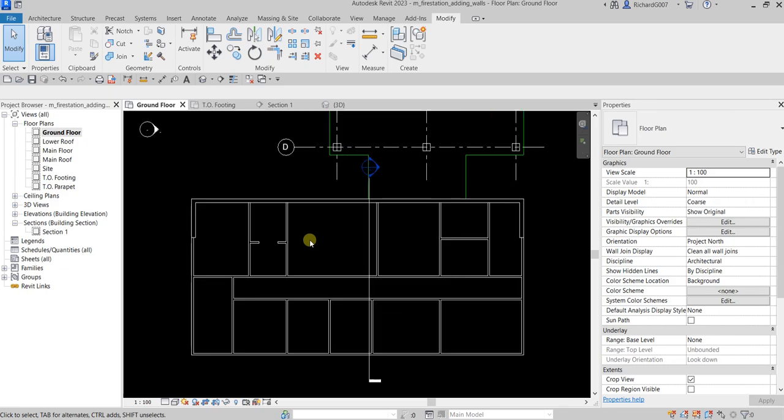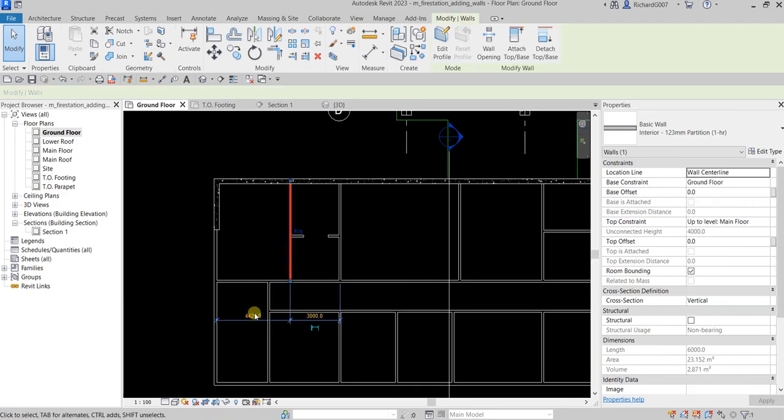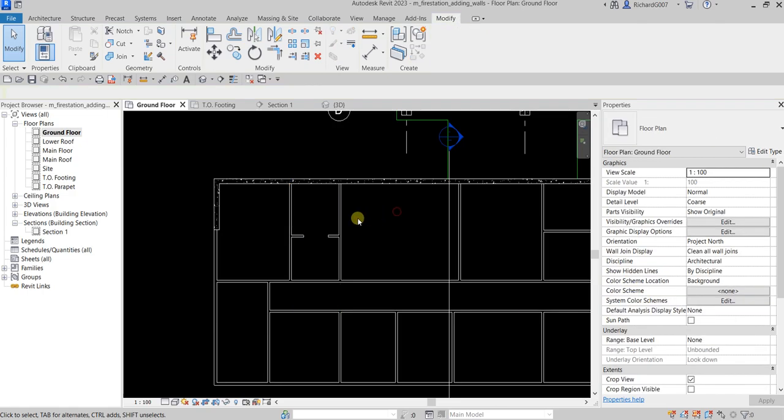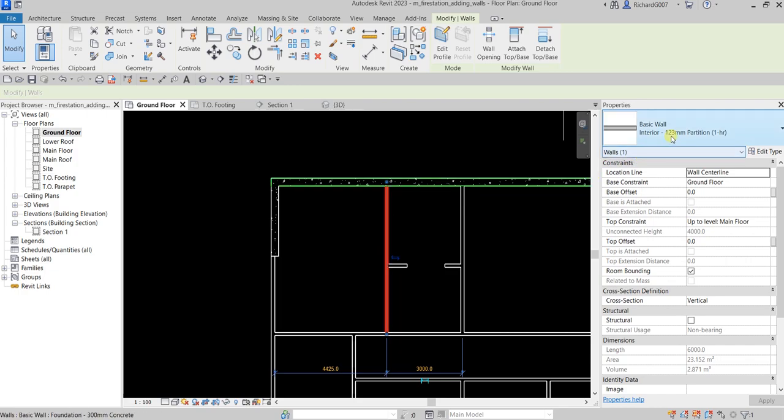Again, to further modify the distances of your wall, you can always select that and change the distance or the temporary dimension of your walls. So basically that's how the wall works, and also how you create a new type of wall. Let's say you want to create a new type of interior wall. You can select that one, use this type, and then select your edit type.